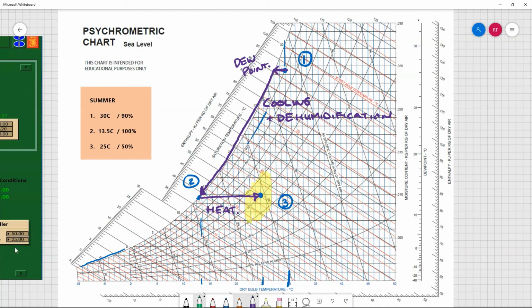It's a lot harder to dehumidify. It's not such a straight pathway. If I was doing my heating, it was just a lot of steps that were bringing me towards my target. This one, instead of going straight down to my target, has to go end around, and the reasoning for that is that I need to drop my total moisture. And one of the only ways to do that is to cool it down until that moisture that's trapped in the gaseous form turns into liquid where I can remove it.